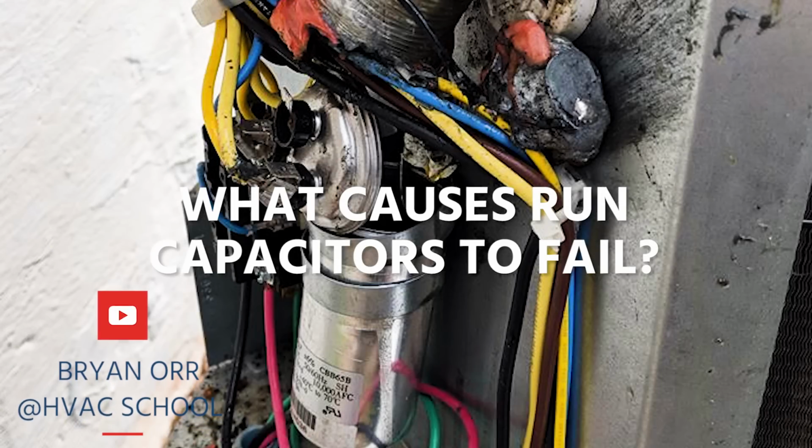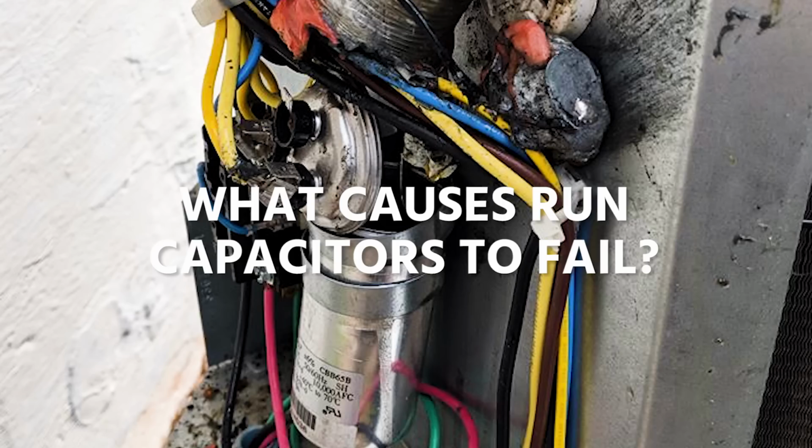So depending on the part of the country that you live in, you may have a major problem with capacitor failure or not. And we notice that in hotter states, states with higher temperatures, we see much higher rates of run capacitor failure. Now, the first thing about this video, if you don't hear anything else, I want you to hear that this is about run capacitors.